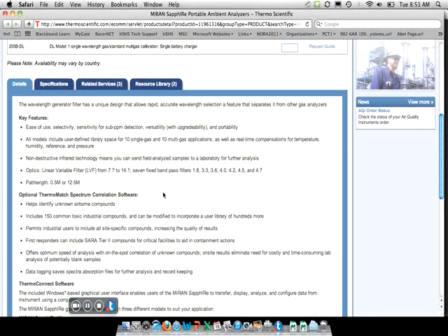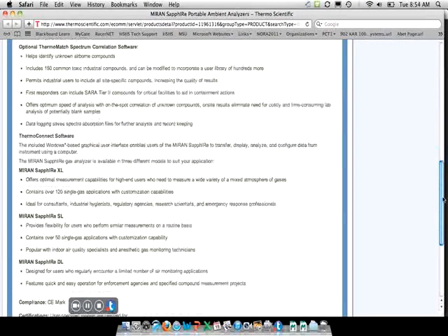But if you go into an area where you know you have multiple different gas exposures that are common solvents and can absorb ultraviolet light, you can monitor for many of these simultaneously. Or if there's one that you're not sure what it is, you do have unique identification based upon absorption. So there are a lot of applications for this particular type of instrumentation.